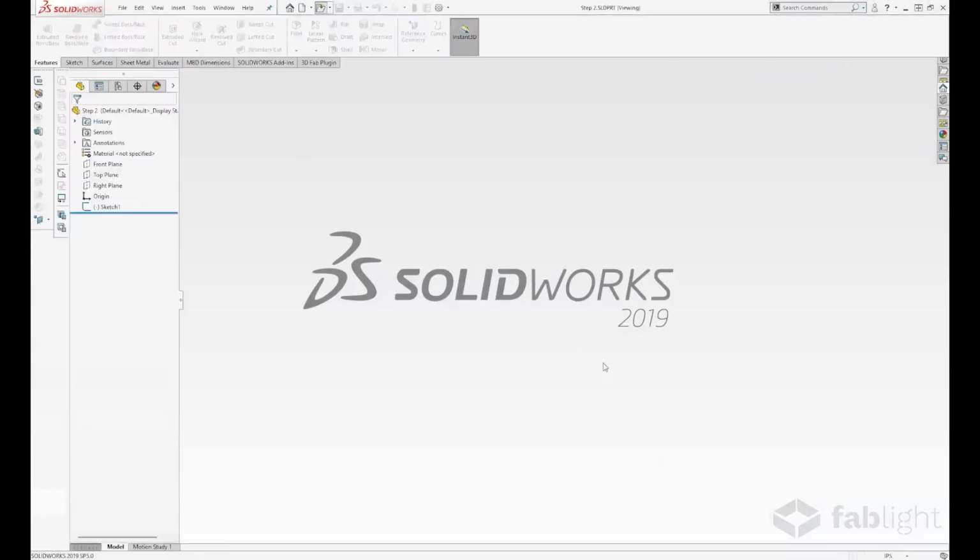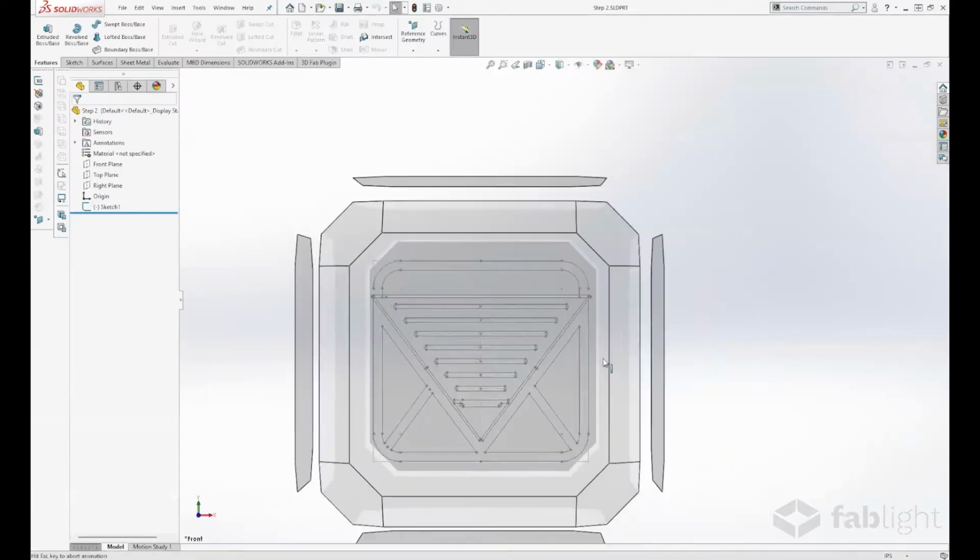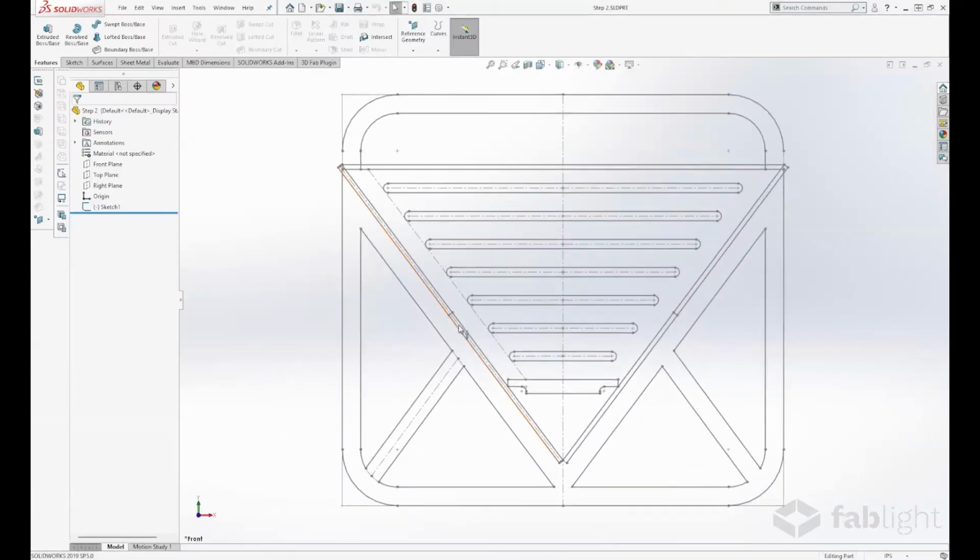Step 2. Now, I'm going to take a little bit of a jump here, but it's hopefully not hard for you all to imagine what we did here. All we did was inset this line out here and offset it by 1/2 inch to match again with the rest of this handle. And then we created another line that was parallel to this side slot here and offset it by I think about 1/4 inch down from this center line so that we could create some open holes, again, to reduce the weight of this.